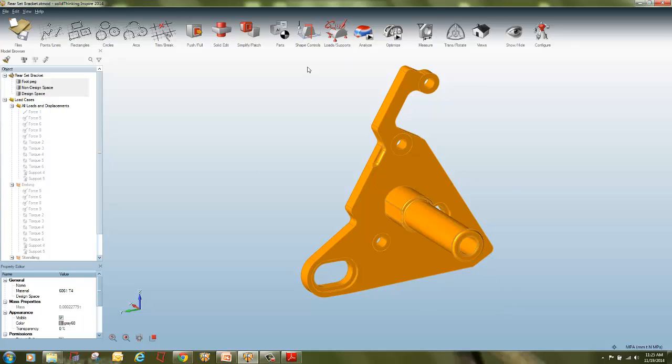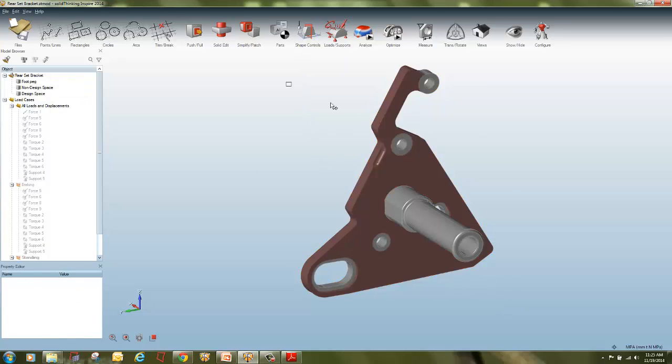You don't have to drag it completely. If you drag it a little, it will select. But if you drag from right bottom to left top, when the object does not completely come under the selecting window, it will not select the object. It should come completely under it, then it will select the object.